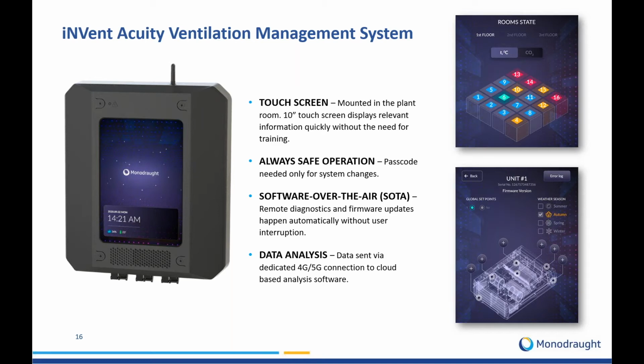And if I just draw your eye to the top right-hand side, that is where the systems link into a building network. We have developed our own communication protocol similar to a Modbus type connection, but rather than having a single assigned number, the systems will self-assign. And by having this grid pattern, we can automatically do a self-discovery, and the individual floors will pre-populate with the systems that they find.